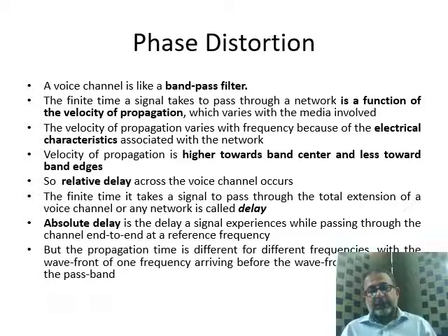The finite time it takes a signal to pass through the total extension of a voice channel or any network is called delay. Absolute delay is the delay a signal experiences while passing through the channel end to end at the reference frequency. That reference frequency can be taken as 800 Hz in the case of European standards and 1000 Hz in the case of American standards. The propagation time is different for different frequencies, with the wavefront of one frequency arriving before the wavefront of the other frequencies in the passband.